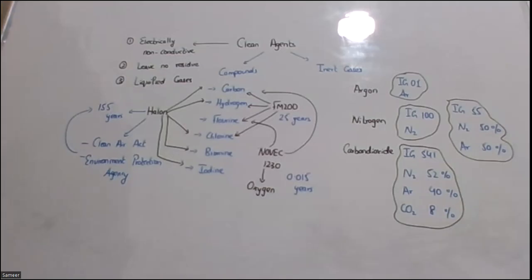In the next lecture, we will complete section 17 by discussing the foam systems. We'll be discussing the AFFF foams, triple FP foams, and low temperature foams. Then we'll see what antifreezing agents are usually used inside the foam systems so that the foam system can be used at lower temperatures. Then we'll discuss the characteristics of the foams, in which we'll see the extinguishing mechanisms of foam systems, and why they are considered one of the most effective agents only for liquid fires. What are the limitations of AFFF and triple FP foams?